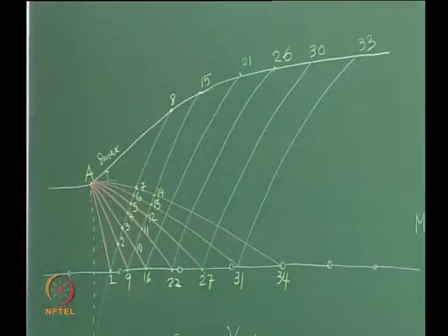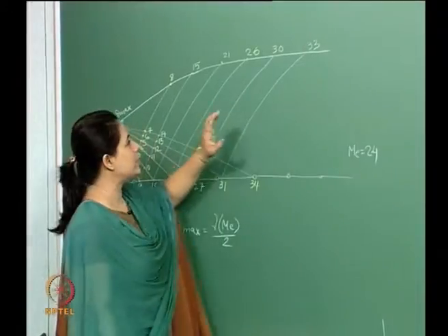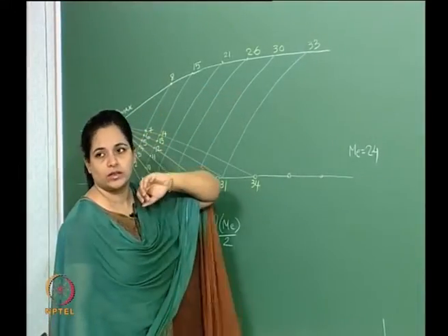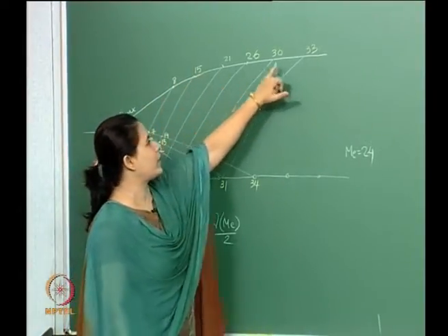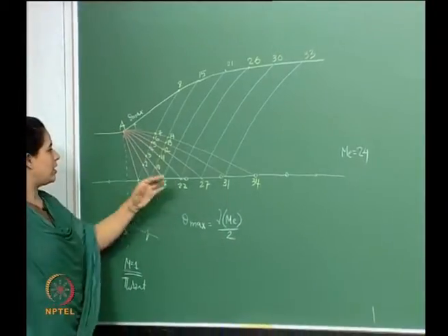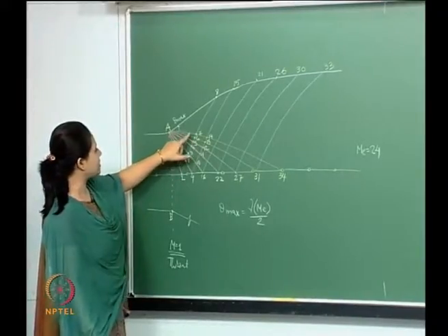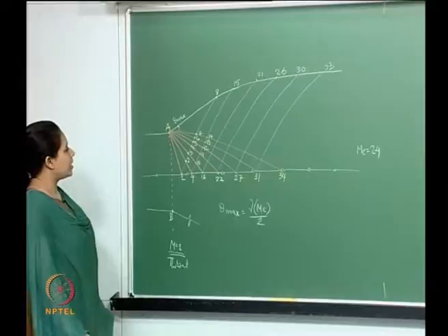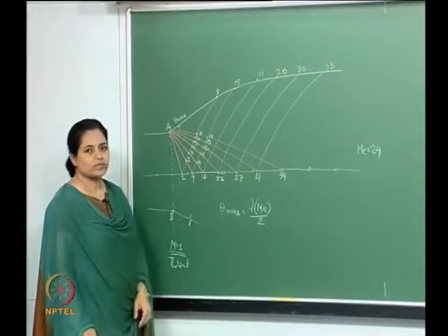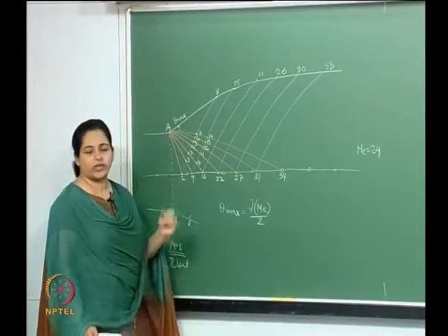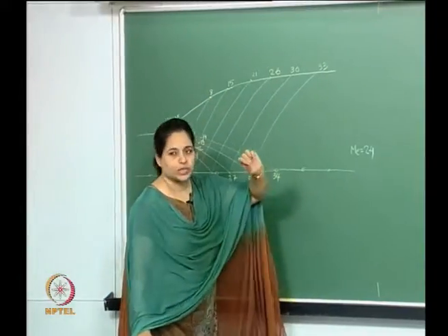what we have to do here is to design this nozzle, which means I need to find locations of various points on the surface, and I have basically 1, 2, 3, 4, 5, 6. When I consider an expansion fan with as many Mach waves out here, which is say 1, 2, 3, 4, 5, 6, 7. Okay, if I'm considering a wave front, which I'm dividing into say 8 divisions, I have 7 Mach waves going in here, then I have essentially 1, 2, 3, 4, 5, 6 points on this surface.